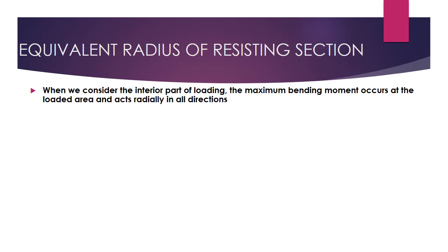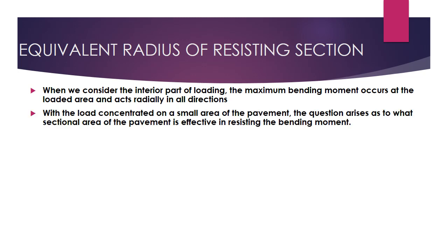Now when we consider the interior part of the loading, that is somewhere in the middle of the section that we have just seen, the maximum bending moment is going to occur there at the loaded area, and it will act in a radial manner and in all directions. With the load concentrated on a small area of the pavement, a question arises as to what sectional area of the pavement is effective in resisting the bending moment.